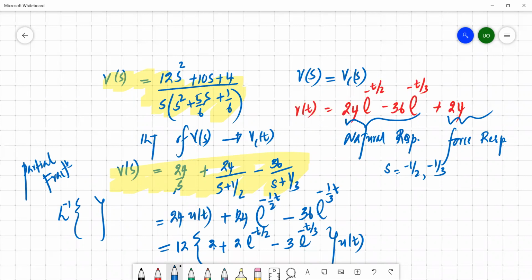by the forced response. So rather than doing everything in the time domain, getting this differential equation and solving it, you can immediately convert this time domain circuit into its S domain circuit by replacing the time domain inductors and capacitors with their corresponding equivalent models, and do the calculation in the S domain.